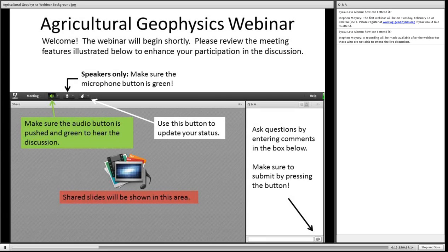If you have any kind of reasonable or high conductivity in the soil, the in-phase component of conductive response will mask the in-phase component of susceptibility response.